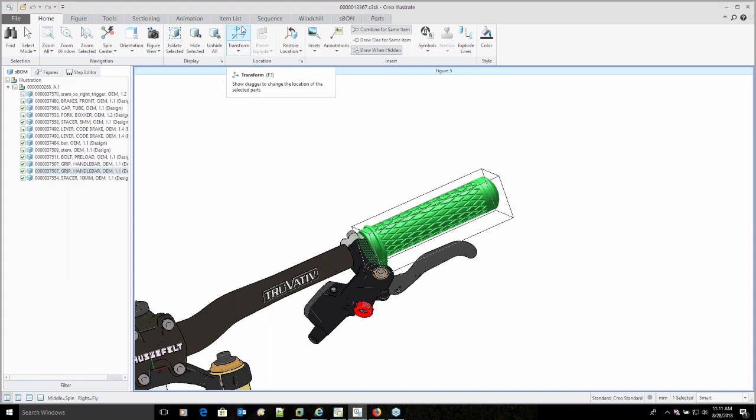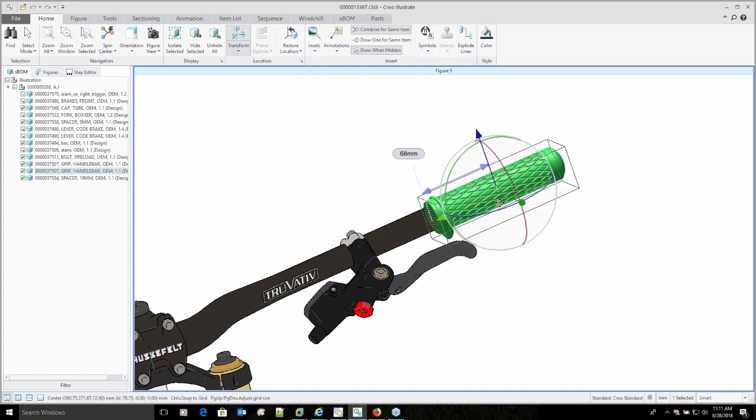There are keyboard shortcuts for that, but I'll go ahead and show you in the ribbon where that lives. It's F3 for my transform, and I've also got a rotation, so I can either rotate that or transform that. If we select linear motion there, you see that I have this gimbal that pops up, and I can grab on the hoop or the arrows and drag that component to its new location. We have the coordinate system here that's integrated inside that part, so we're really showing the XYZ coordinate system of that part. So just simply drag that off.